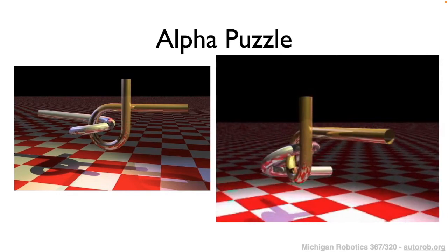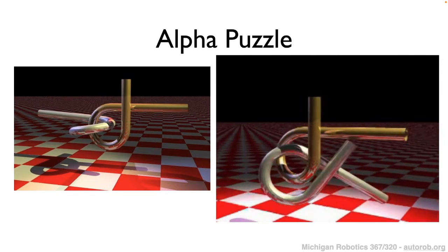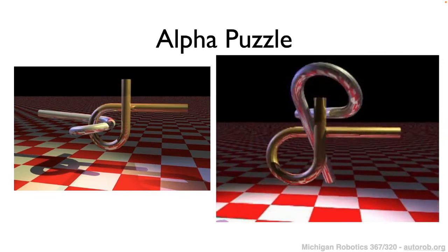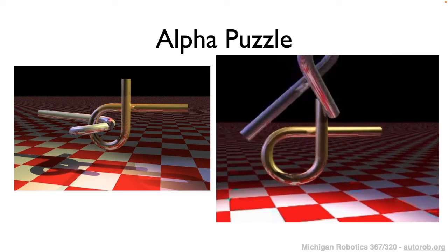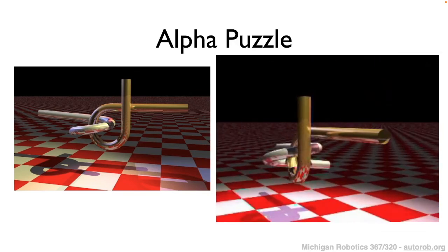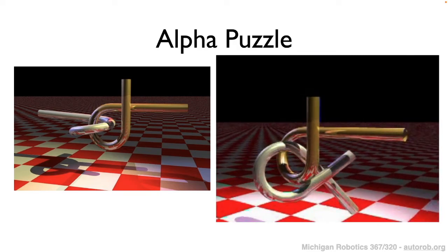But in addition, there's also cases like this particular case, which is really pretty neat, where geometric puzzles could even be solved using RRT Connect, because once again, you can represent the pose of the puzzle pieces as taking on points within a configuration space, and then correspondingly try and find a path through configuration space that would separate the poses.